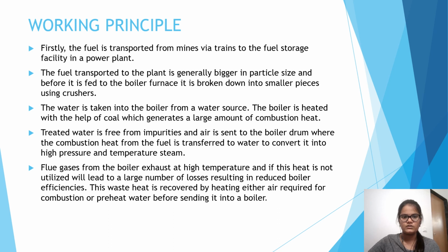The water is taken into the boiler from a water source. The boiler is heated with the help of coal, which generates a large amount of combustion heat. Treated water, free from impurities, and air are sent to the boiler drum, where the combustion heat from the fuel is transferred to water to convert it into high pressure and temperature steam.